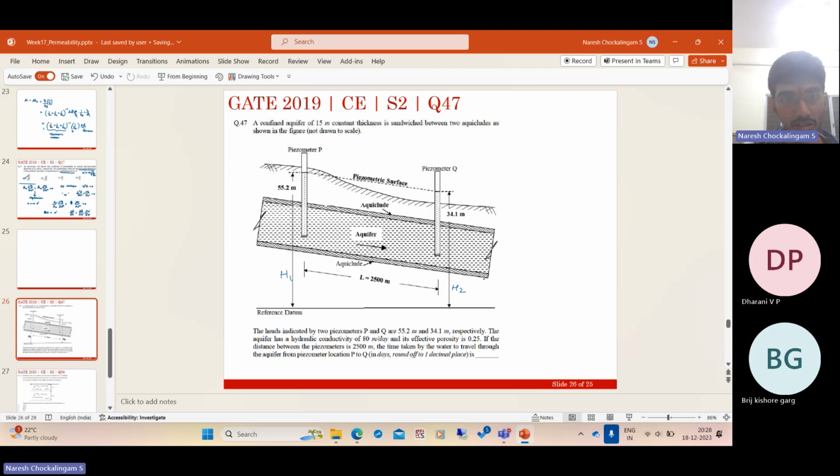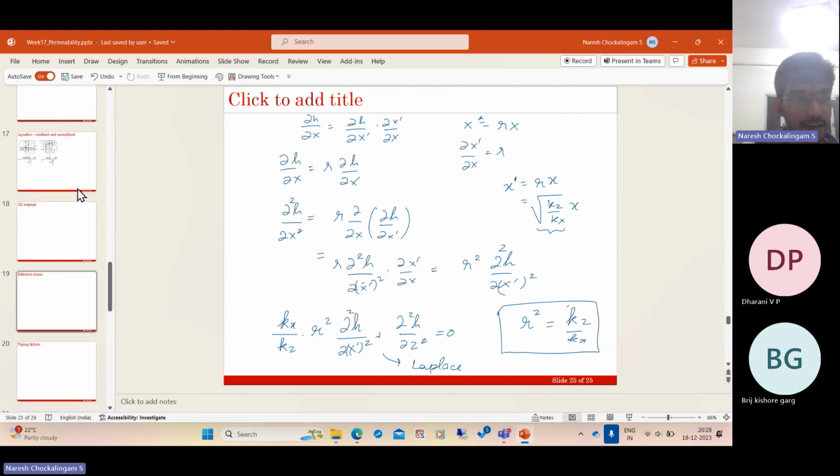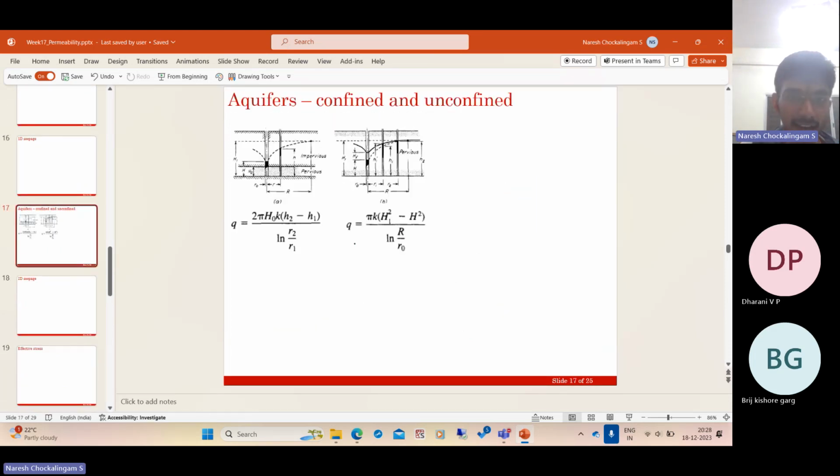This is a direct application of Darcy's law. So looking at the aquifer directly, don't get into this formula, right? That's a common mistake. This formula you might learn. I'll derive it and put it, but this is something people remember, and it is a very commonly asked question. People try to remember this, but it holds only when you're pumping water out of a borehole.